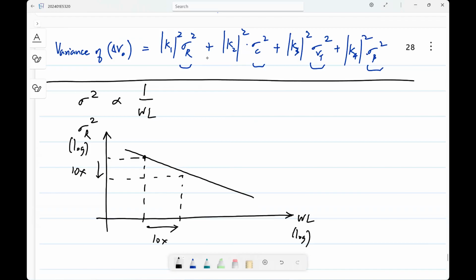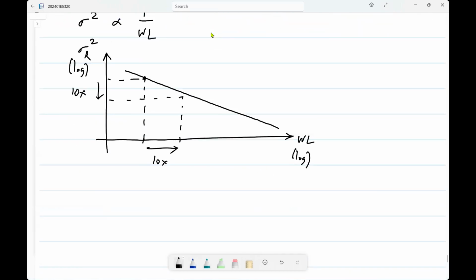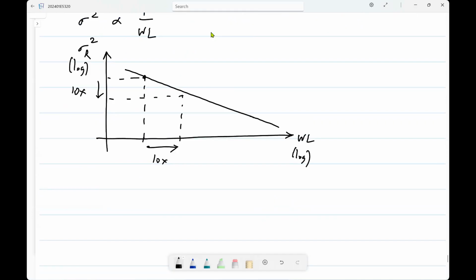Now there is one more effect that comes into this matching, which of course is hard to calculate. We won't do it, but this one implies that if you go on increasing the area, the mismatch will go on decreasing. Of course, you can't reduce the mismatch by very large factors in practice because you can't have area going out of control. As I mentioned, on an integrated circuit, area is cost. But even besides that, there is another thing that affects matching.